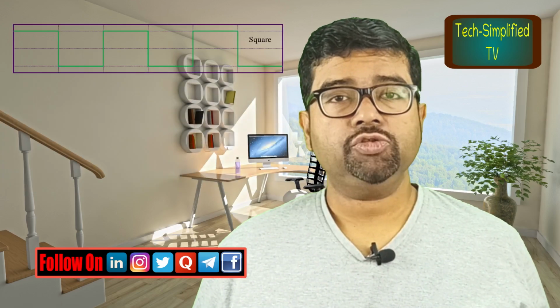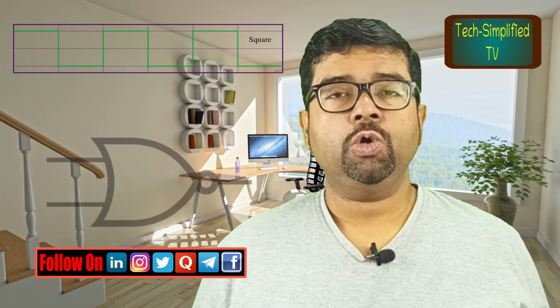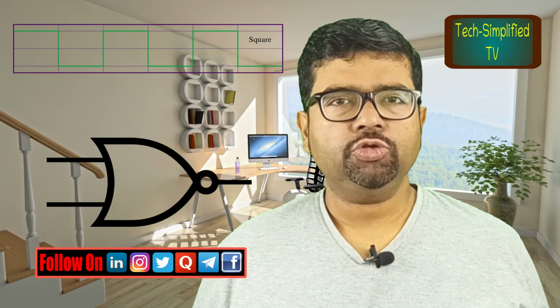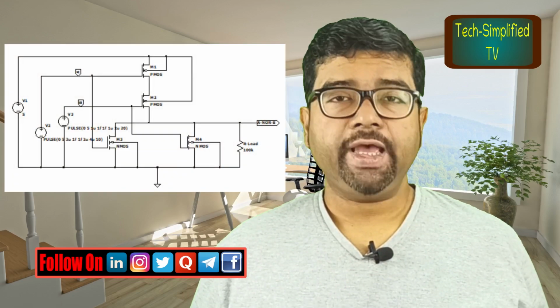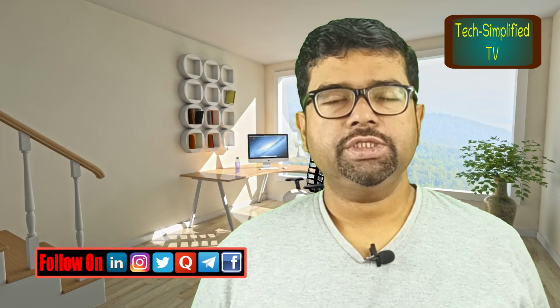We will apply pulsed waveforms shaped like square waveforms as the two inputs of the constructed NOR gate. The two square waveforms have different on-time and off-time to cover all the truth table combinations of the two input NOR gate. We will apply proper DC biasing and transient analysis to check the functionality and performance of the constructed NOR gate. So stay tuned, stay focused.